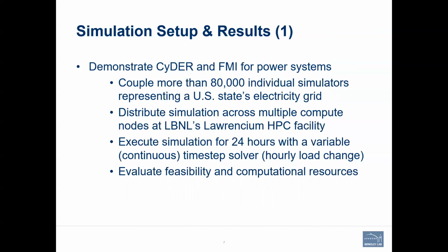We distributed the simulation across multiple compute nodes at LBNL's Lawrencium high-performance computing facility. We executed the simulation for a 1 day period, so for 24 hours. It did use a variable time step solver. However, we only had an hourly load change, so at the end, it's basically an hourly profile. And then we evaluated the feasibility and necessary computational resources, which I will speak about in a second.